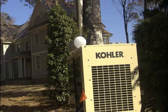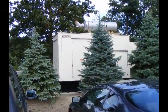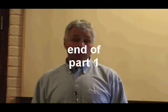What about foliage? Foliage doesn't necessarily burn, but we don't really find too much of an issue with the foliage catching on fire or burning. We don't have that much of an issue with the towns. I mean, if it's up against the machine, like hemlocks grow like wildfire. Today it's fine. 2 weeks from now, you have a forest. So if it gets too close to the machine, it will restrict the airflow, and you really need to be careful of that. The towns like to see foliage around the generator so that it improves the appearance, but that does not mean up against the generator. Our rule from the service side of the equation, 2 feet. We need 2 feet to service this generator properly. So if you want to put a tree, at least give us 2 feet.